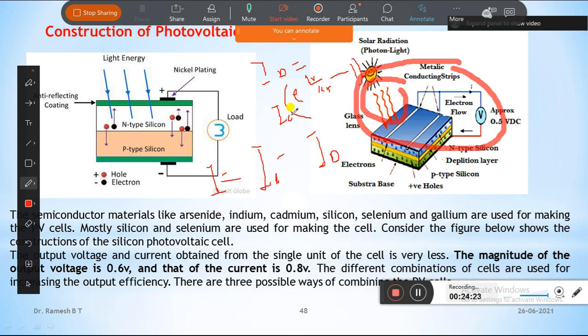And the fill factor, called FF, is a very essential measure of the quality of the solar cell. It is calculated by comparing the maximum power to the theoretical power that would be the output at both the open circuit voltage and the short circuit current. This FF can also be interpreted graphically as a ratio of rectangular areas.